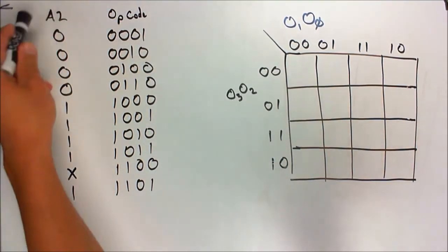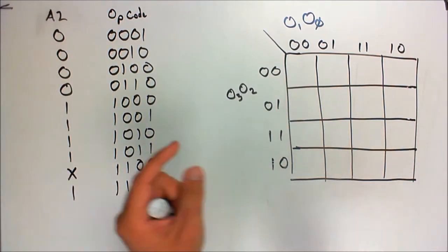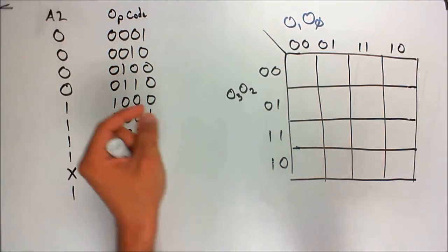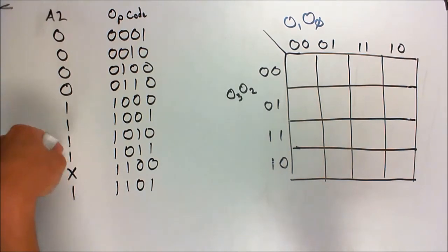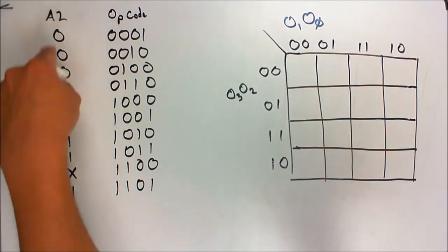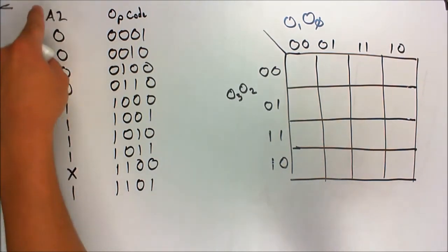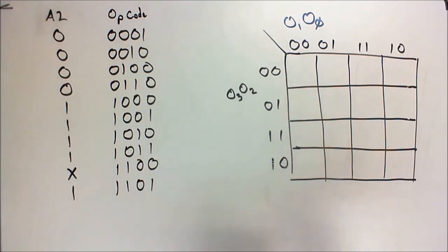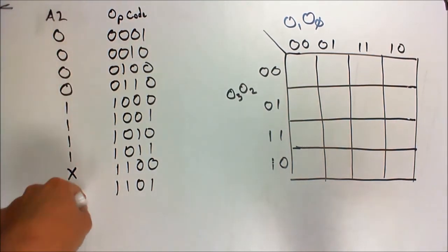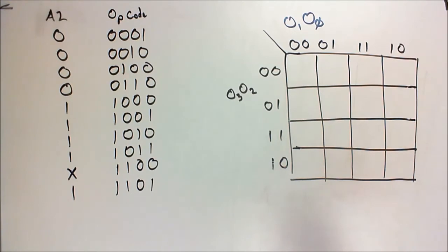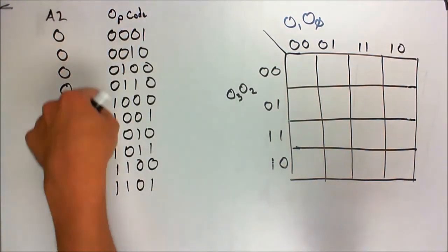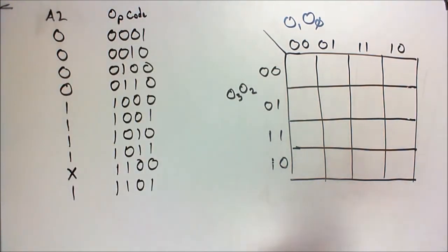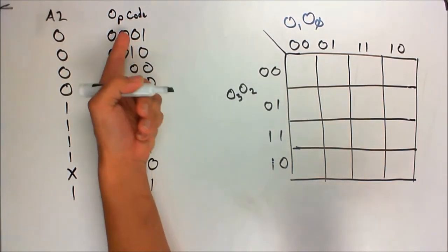So of the 3 bits that make up the ALU operation, this is the most significant bit. So this is the leftmost column of the ALU opcodes. And all I've done is strip it out so we can work on it individually. And I've only listed the non-zero opcodes here because for all the other instructions that we have available, the opcode is 0.